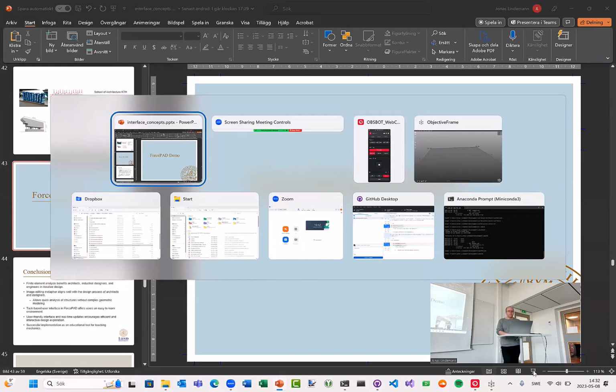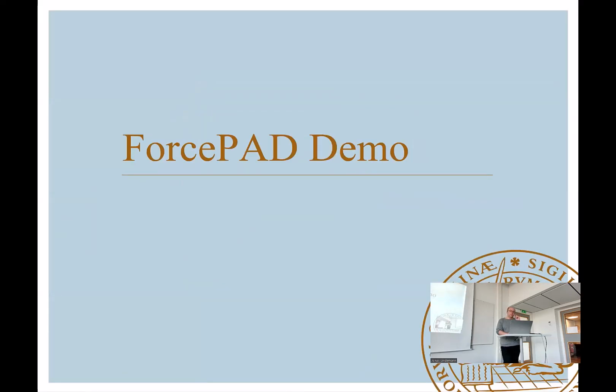But from that, can you assume it should be an arch, or do you have to have all those other things in the structure? No, it can generate. So you can set the ratio how much material you should save. And I put a bit too little, so it removed too much now. But if it's constrained in both directions like this, you will get an optimal arch shape because it's a dead load weight, and then you get the optimal.